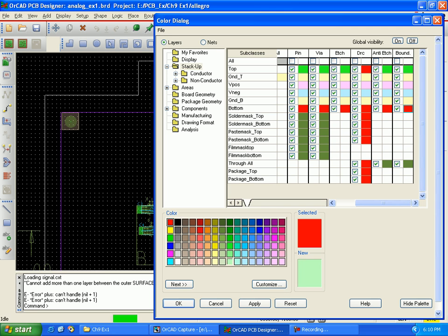So make sure the solder top and solder bottom are there. These are the layers we need because we want to place the SMD on them. So we need a mask where we want to put the solder. There are two sides of the PCB, top and bottom. These are the particular regions where the SMD is going to be fixed.